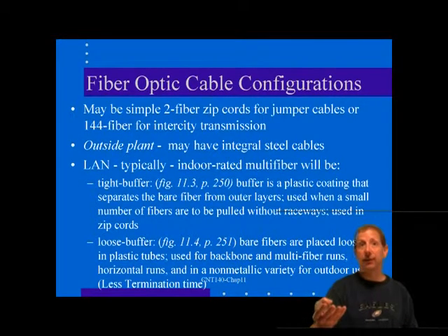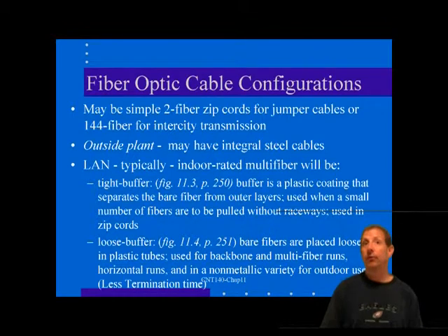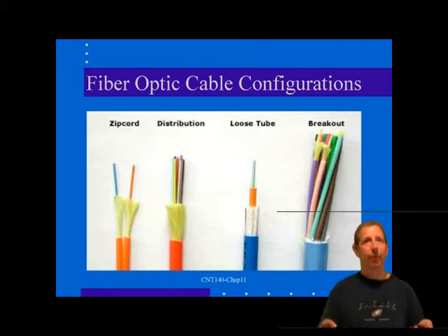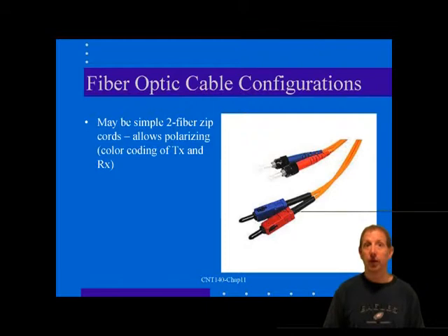In addition to the inside plant cables, several types of loose buffer cables are offered for outside plant. A non-metallic direct burial cable, sometimes called a dielectric cable, is one type. This cable is somewhat more impervious to lightning damage, but be assured that if the cable is run alongside metallic cables, as is frequently the case in aerial runs between telephone poles, a direct lightning strike will blow a hole in this type of cable just the same.